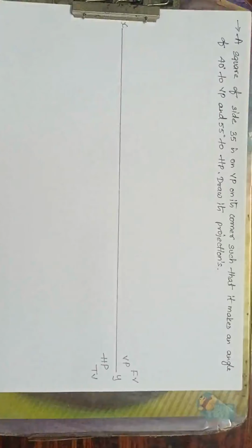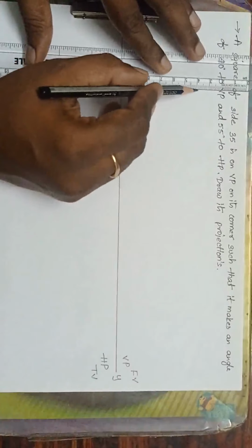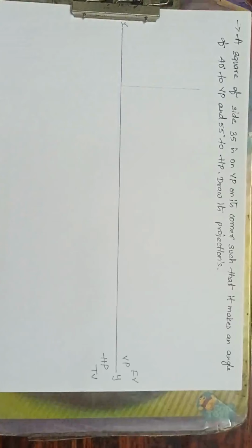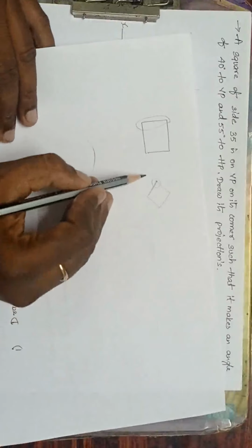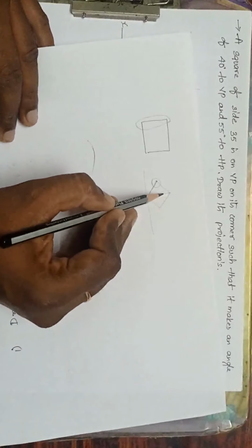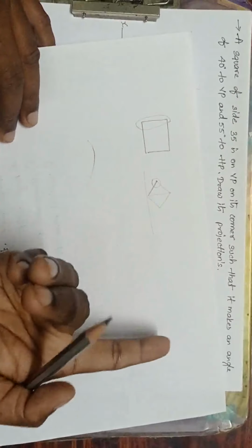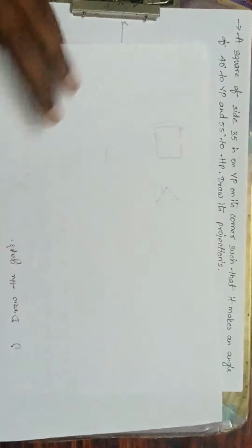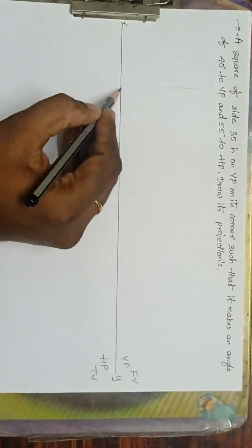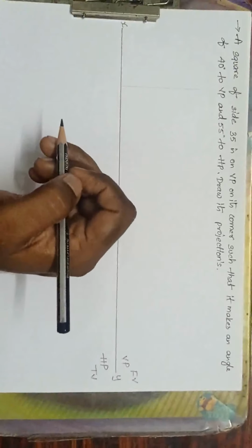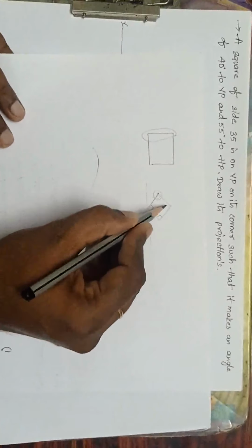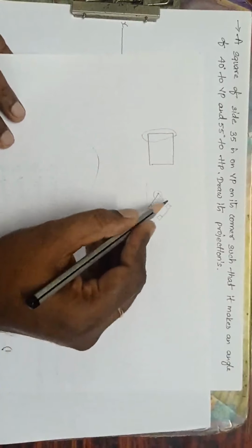Fine. What I'll do is, for the corner, first I'll draw any line, some line like this, a perpendicular line. Why? Because see, this is like this. So this perpendicular line is the diagonal. I don't know the length of the diagonal, but I know the side. He has given side 35. Here I know that the square is having 90 degrees on the corners.